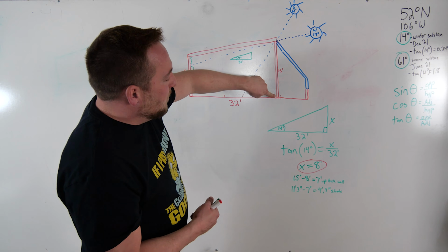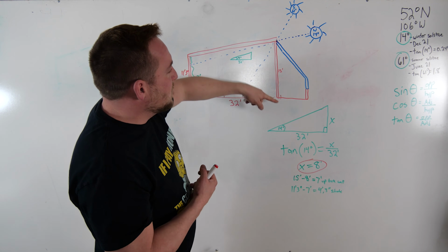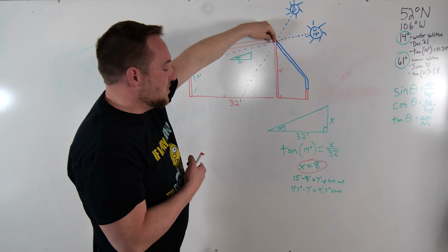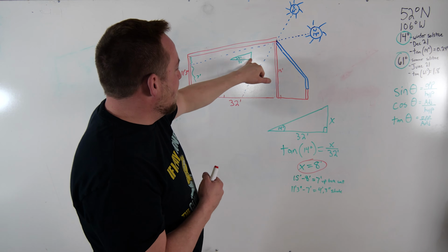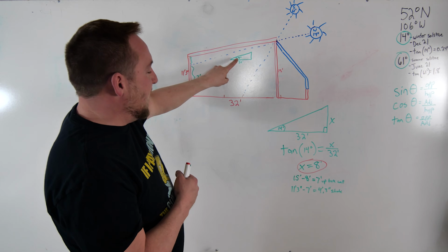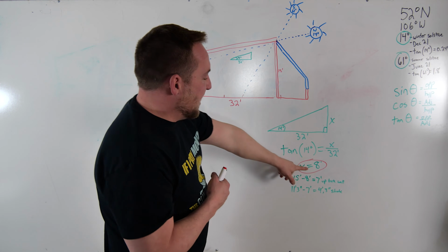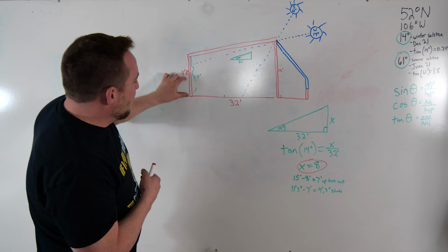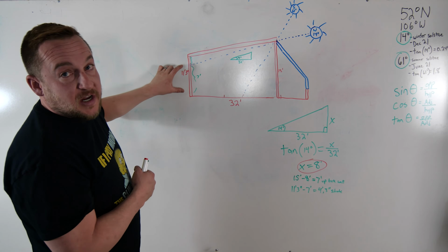So my post from the finished concrete to the underside, where the shading function starts, is 15 feet. So in the triangle that we made to utilize that 14-degree winter angle, it's 15 feet minus the 8 feet that we came out with, equal to 7 feet up the back wall is where my sun is.